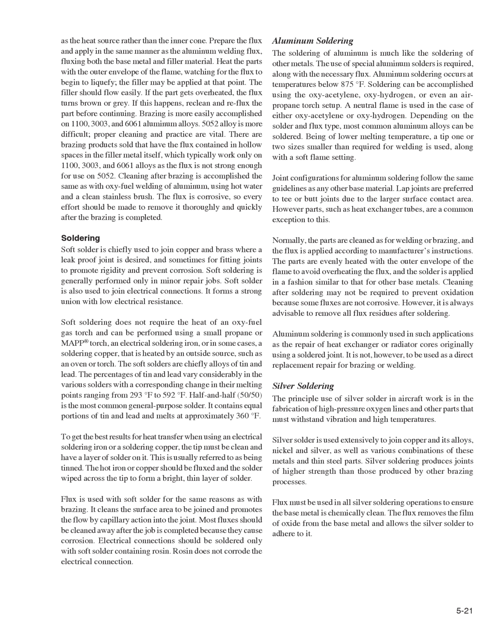Cleaning after soldering may not be required to prevent oxidation because some fluxes are not corrosive. However, it is always advisable to remove all flux residues after soldering. Aluminum soldering is commonly used in such applications as the repair of heat exchanger or radiator cores originally using a solder joint. It is not, however, to be used as a direct replacement repair for brazing or welding.